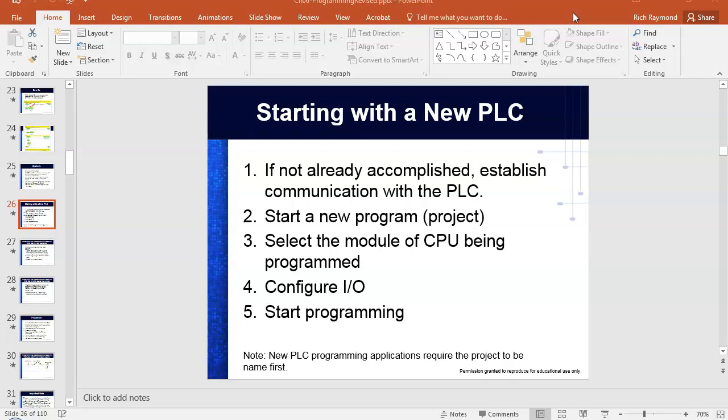So this is RS-232. The problem is that the RS-232 port is not available on computers anymore. What dominates everything now is Universal Serial Bus. But we can still get the older interfaces by buying what we call dongles. So this is a dongle, and what it does is it takes USB, this is what we call a standard B connector. This is the first one they used on USB. Now they've gone all over the place. They have a micro-B now. And then it converts over to all the pins for the RS-232 interface.